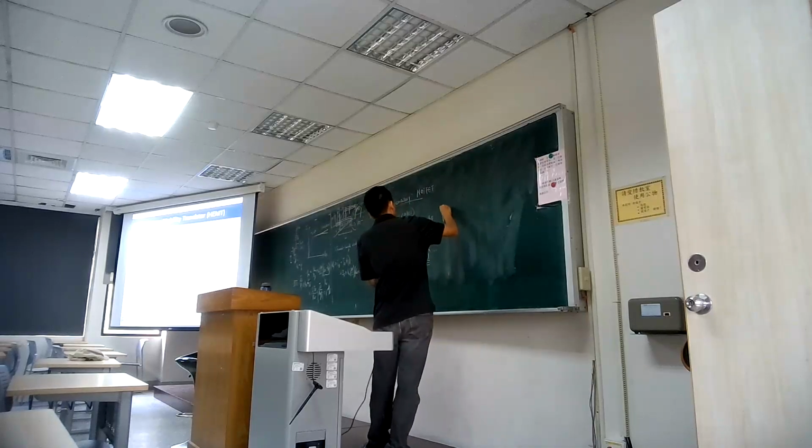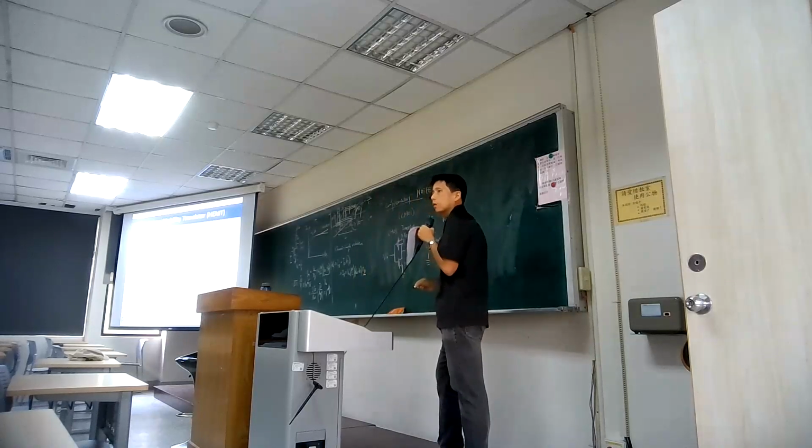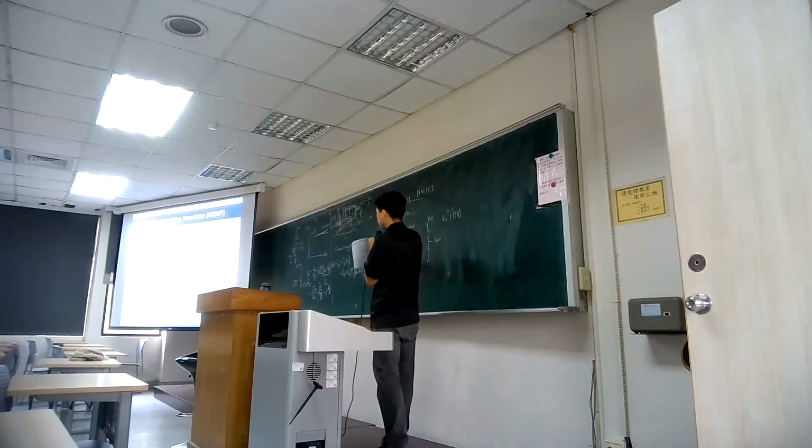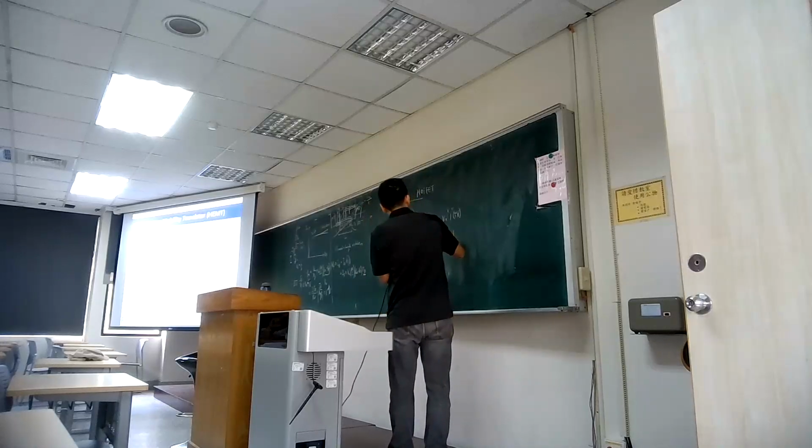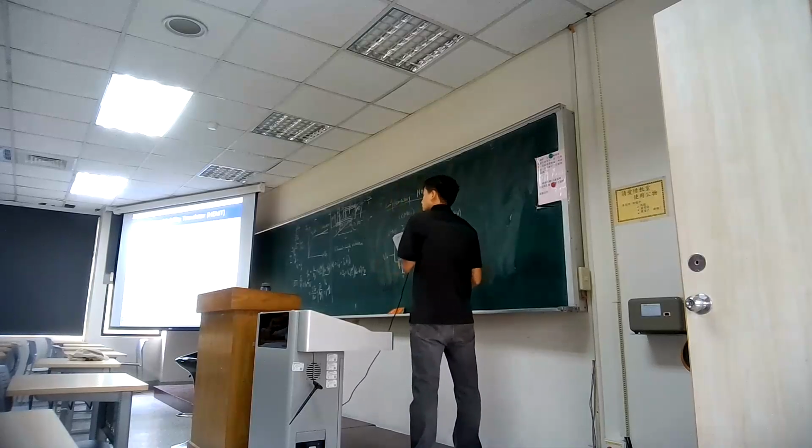Why we get this is because when you input Vin, it's 1 V. But then you are working with VDD of 5 volts for logic operations. What happens is that if you get a high voltage here, the NMOS is almost on. But for PMOS, you get the same voltage, so there is no inversion channel. If you are working with this one, you only get almost on.